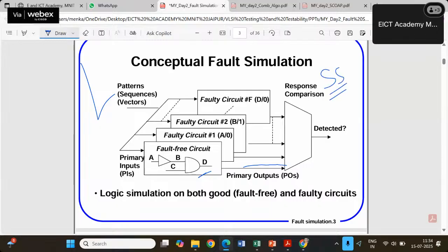Yesterday we discussed that a single stuck-at fault is going to cover multiple stuck-at faults altogether. So we will only cover the single stuck-at faults, and that too using the checkpoint theorem, we figured out that if we have the faults only at the inputs, then it will be okay. We will be able to cover most of the faults if these are reduced to the input faults and the fan-out branches only. So what we are going to do is, at a time we will take one fault, and according to the fault sites, we will create multiple copies of the faulty circuits.